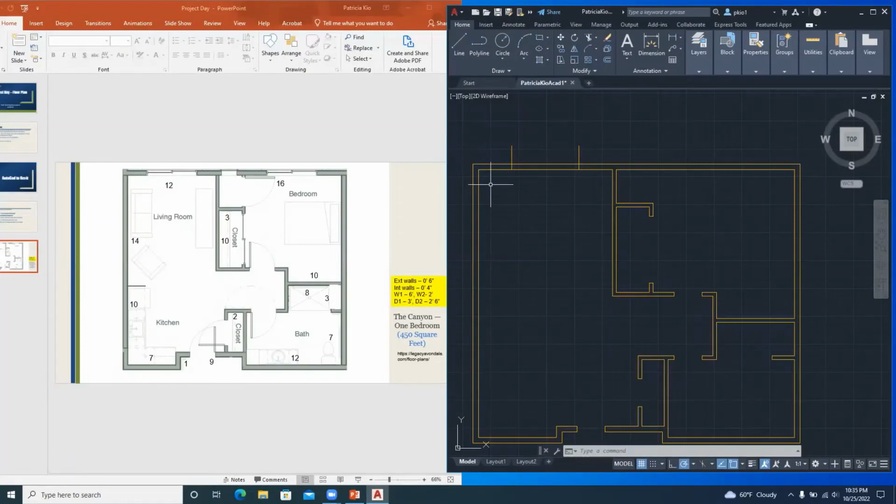You want to put your windows anyhow. So I'll mirror these windows so that they appear at equal distances from the edge. To do that, I will select the 2 lines. This is a mirror tool, and then look for the center, that triangle, and then drop it. So now we can trim.